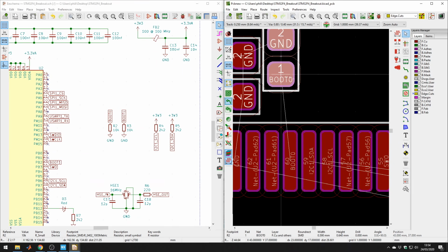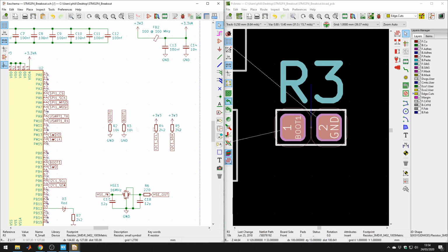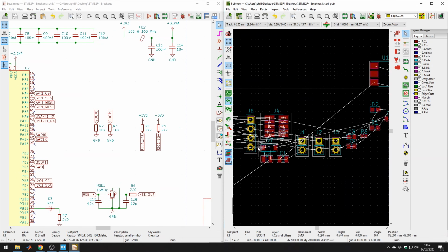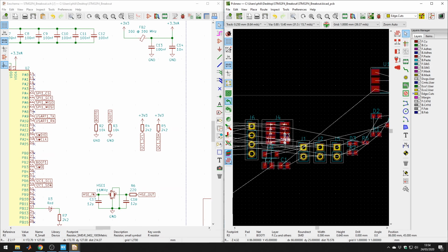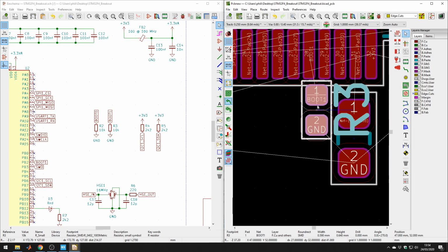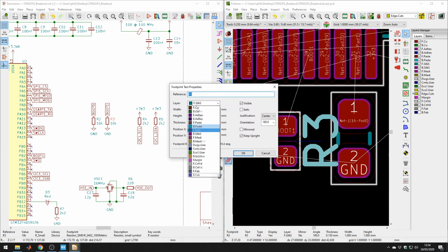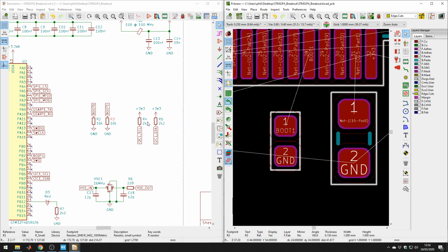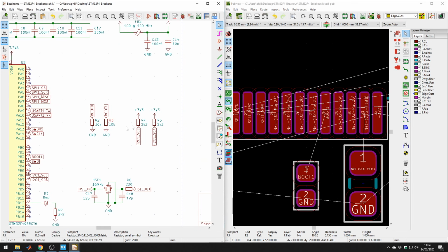I don't want to put it somewhere around here because I'll just block these pins. So always be aware of that, just kind of a forethought. You can do everything in the moment, but you're probably going to have to change it in the future. So put that here. And then pull up resistors, let's do that later because they can be next to the output pins as well.